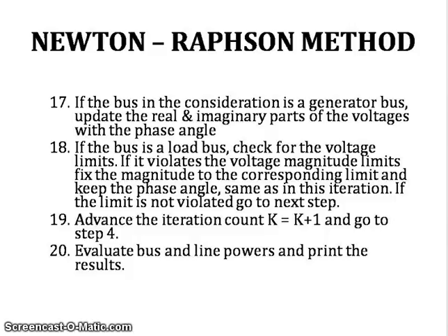We will have equations with respect to active powers. Similarly, functions of voltage and angle in terms of reactive power. Then we need to find the vector of corrections delta x corresponding to delta V and delta delta.